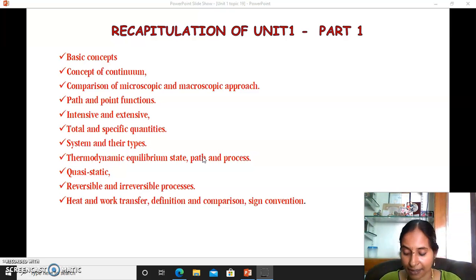The ideal gas temperature scale does not depend upon the nature of the thermodynamic or thermometric material. The International Practical Temperature Scale was adopted by the International Committee of Weights and Measures, and is based on a number of easily reproducible fixed points together with the methods of interpolating between them.